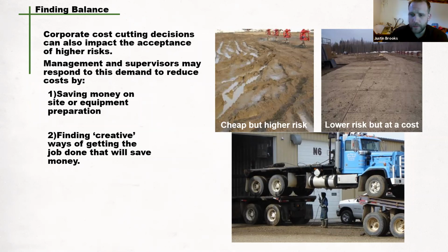The photo on the right shows a site that has rig mats placed to reduce the hazards presented by muddy conditions, a solution that had costs associated with it. And again, rig mats aren't necessarily the only way to handle something like this. I've dealt with these types of sites many times where we've used bamboo matting. We've built platforms and walkways out of wood, depending on the work that needs to be done, right? So there are other ways to handle this. It's not necessarily the one with the highest amount of risk. Even sometimes spreading river rock or rock can help.